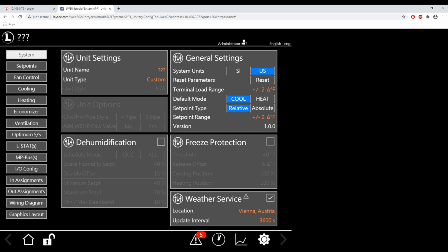Throughout the graphic, different colors are used to indicate different things. White text is used specifically for labels and indicates that a value is read-only. Any text in orange indicates a user-adjustable variable. This could be a drop-down menu for selecting options, or a numeric value for set point changes. Blue is used for selecting options within the configuration settings. A blue background means the selection is active. Gray indicates an option is inactive or invalid based on the current configuration.